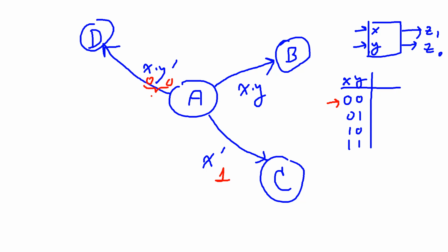this condition becomes false. So you can note that when you apply one input combination into the system, only one transition expression will become true, and the other conditions become false. So when the clock ticks, the state machine will change state in the direction that makes the transition expression become true.